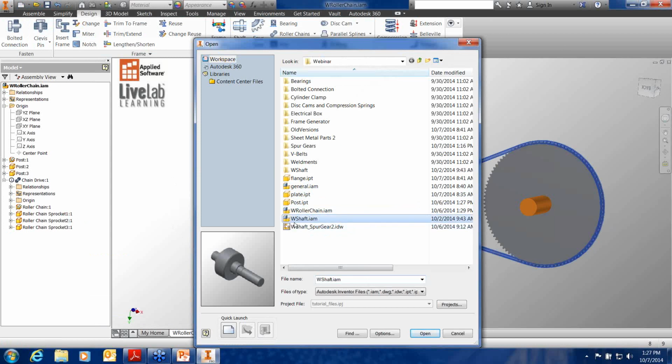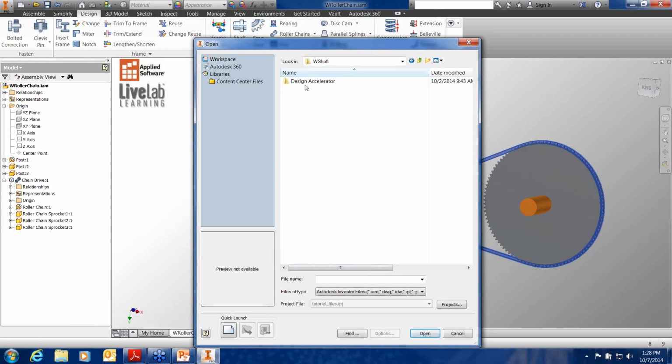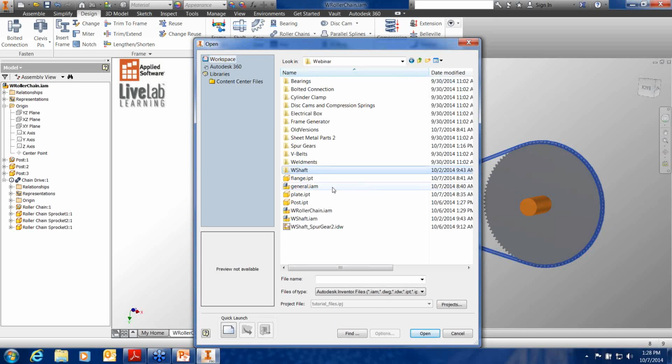It does create these shafts as like little assemblies. And each one of these, I think it will work down the hierarchy. So if we go in, say, and create a particular shaft assembly, it still recognizes it and should bring it into Inventor. Now, I have not actually done that in real life, but since it's recognized as part of an assembly, it would grab anything that's associated with that assembly, which would be the parts themselves, and should bring those into Inventor as well.